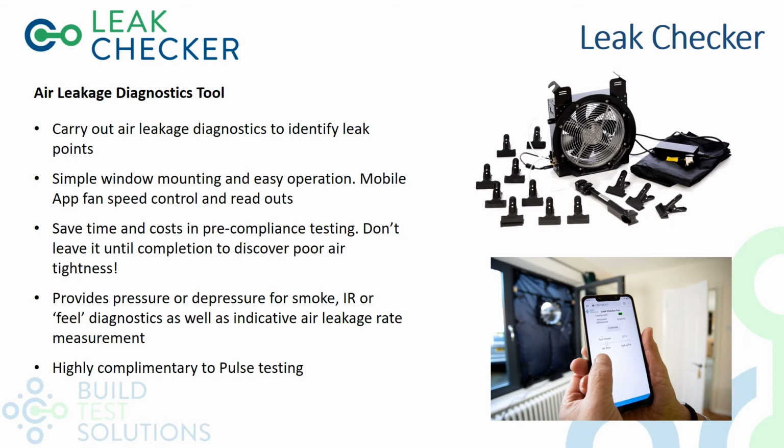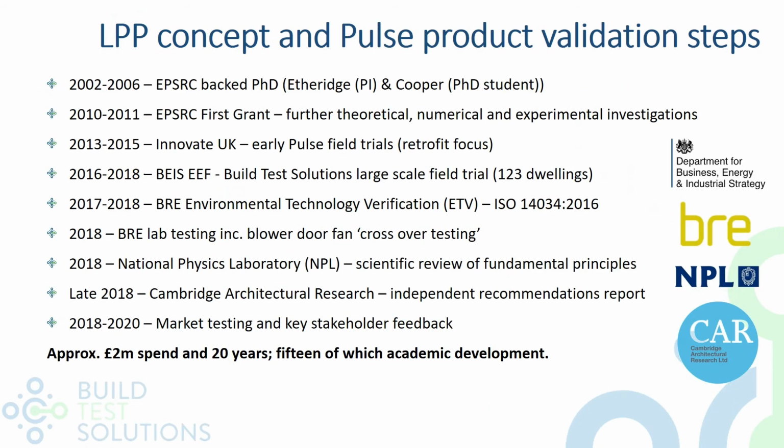So it's not the point at which remedial work should be carried out, and we shouldn't be finding out that a building's too leaky after all of the works are complete, and that all we can do to correct that is use some sealant or expanding foam.